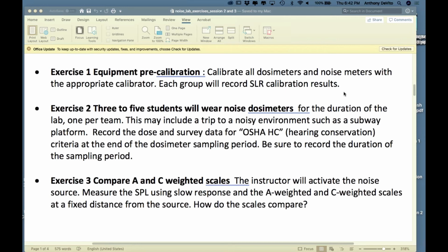In the case of OSHA noise exposure measurements for permissible exposure limit, you calibrate before and after you take any readings. Now you have to make decisions sometimes, like for instance, if you are in a situation where a worker has an 8-hour workday, but that includes a 30-minute break for lunch. So he works 7.5 hours, but he's got a 30-minute break. Well, you're measuring over an 8-hour workplace exposure.